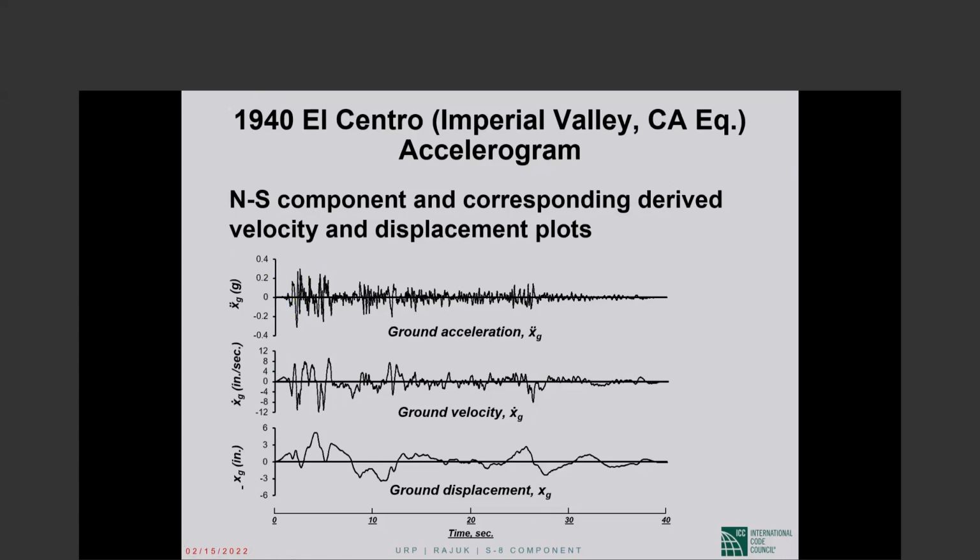Agencies that record these accelerograms pretty much routinely integrate the accelerograms with respect to time, obtaining a history of ground velocities. And you see right away that the ground velocity plot is not as erratic looking as the accelerogram, and also more importantly, the period has lengthened.